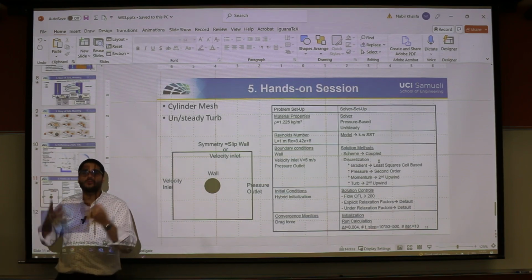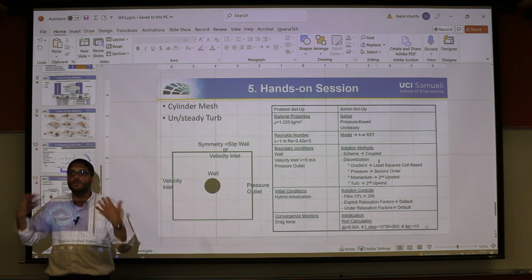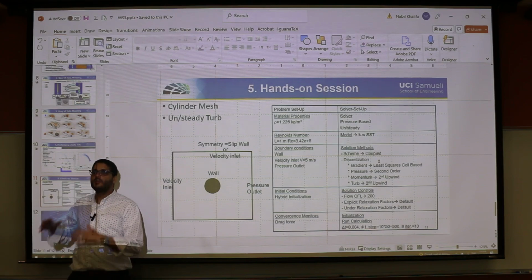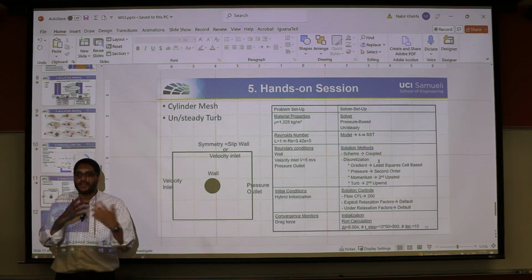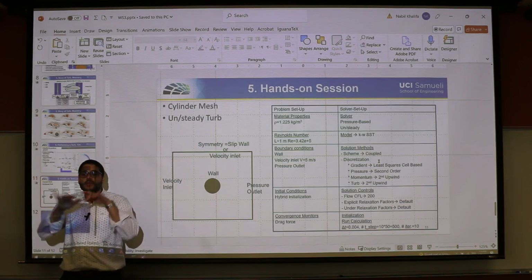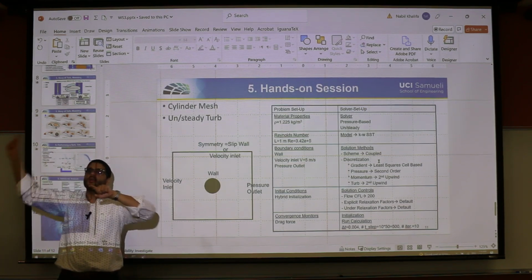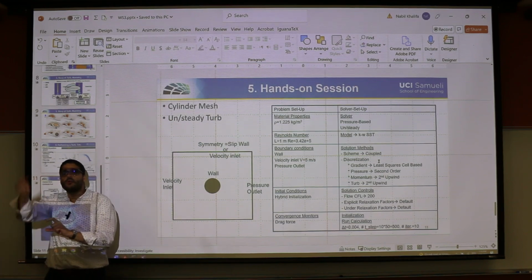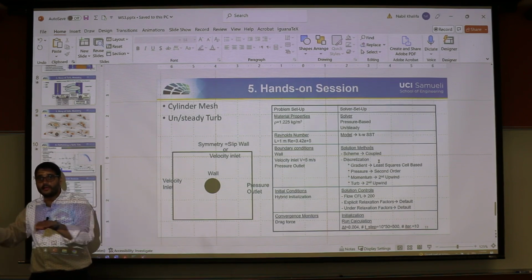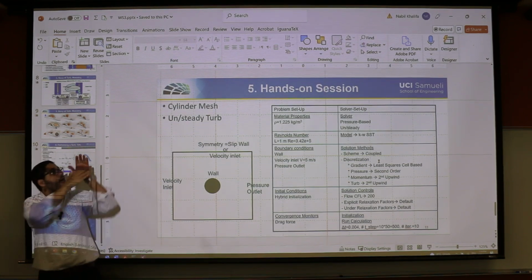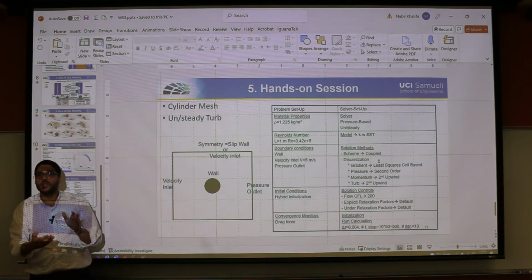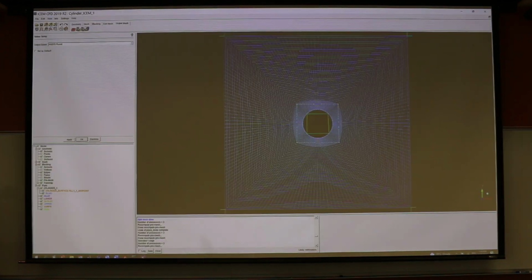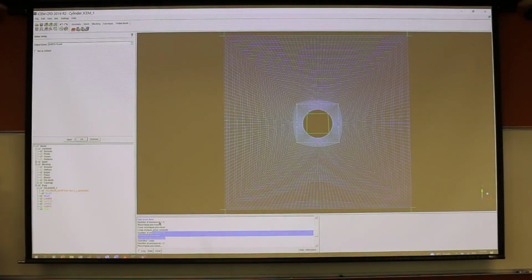What we are used to in using software on Windows are called GUIs, the graphical user interface. But in reality, you can do everything in the TUI, which is the text user interface. Any command or any button that you click on in the graphical user interface, you can have a command that's equivalent to that task and write it in that black console for Linux, and Fluent replies to you in that black command window, in this console.